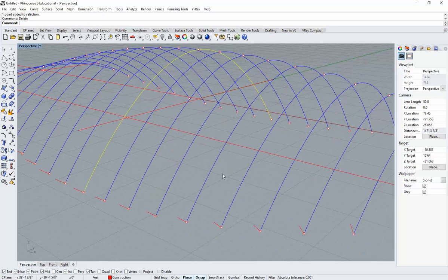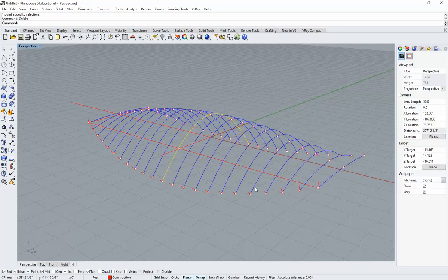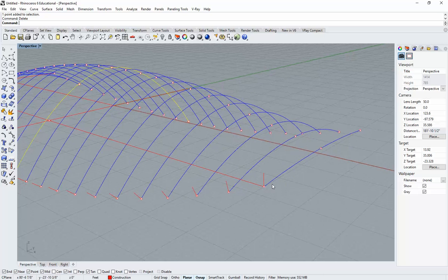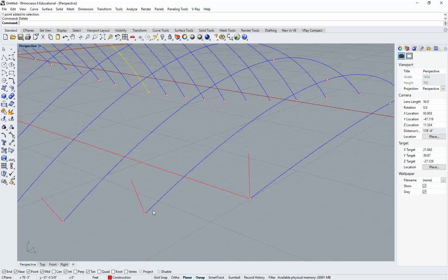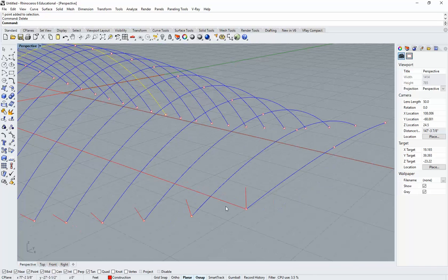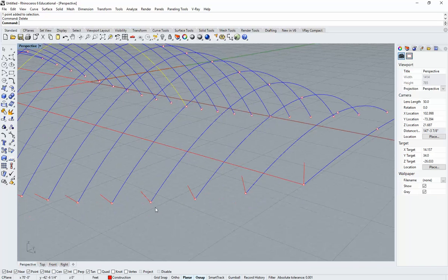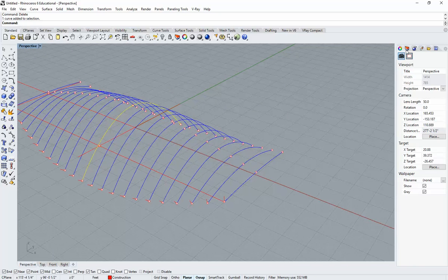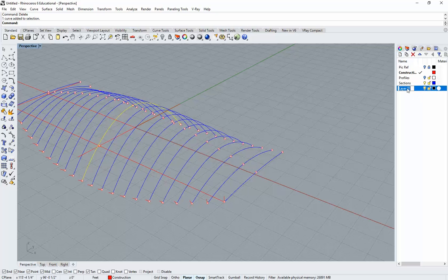Okay, so to wrap up part 1 here, the next thing we're going to do is orient a section profile, meaning the outer edge of the thickness of these beams, to each one of the construction lines we just drew relative to our section line here. Okay. There's a couple ways to do that. I'll show you both. First thing, I'm going to make a new layer.